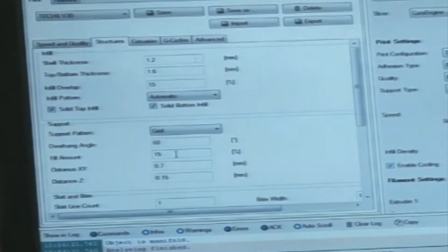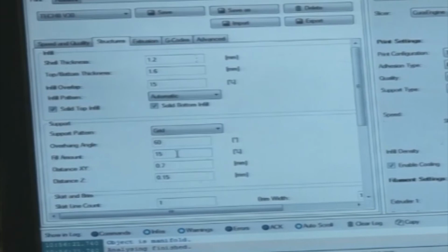So the overhang angle is 60 degrees here. The overhang angle here is for this machinery. If we are going to deposit, or print, or manufacture any job, if it is solid, there is no issue at all. If it is a conical shape, an angle up to 60 degrees is fine.